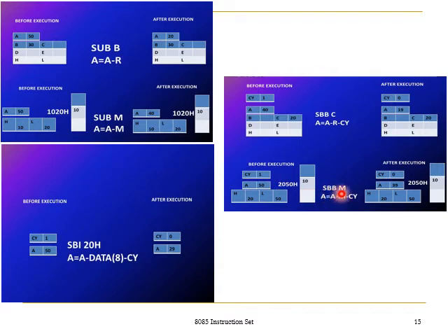And if it is SBB M, instead of the register content it is going to choose the memory location content and subtract. So it is going to take the value 50 from the accumulator, and the memory location is 2050. Here the 2050 memory location has a data of 10. So 50 minus 10 minus the carry flag 1 is 39. The 39 is loaded in the accumulator. This subtraction operation does not produce any carry, so the carry flag is cleared.